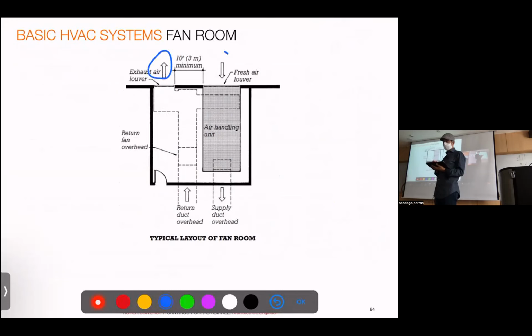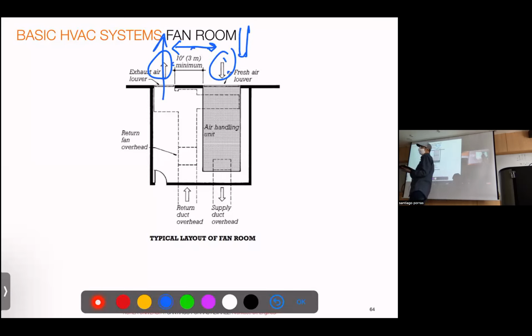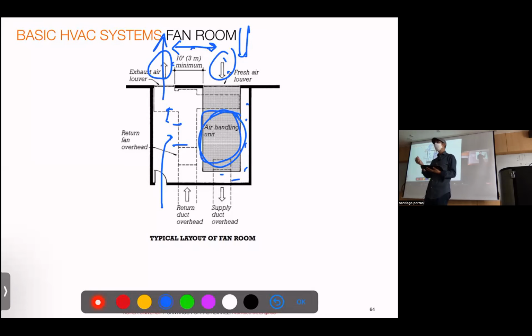if you have contact with exterior, exhaust must be as far as possible from the fresh air. Otherwise, you will have contamination coming in, right? It should be as far apart as possible, or having just a duct going to the exterior, not just the facade. Then you need access so you can maintain the ducts and the ventilators. It's a huge box. You need a space on the borders for people just to make some basic maintenance and cleaning.